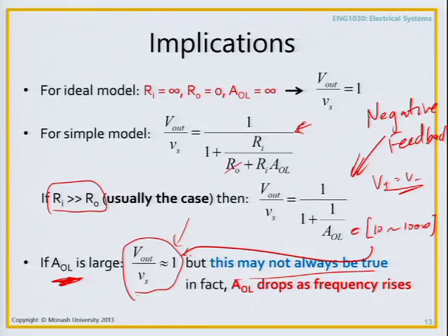Now, if I start putting a few resistors in there, and it's not a unity gain buffer, all the maths is exactly the same, and it will come out pretty much to the fact that AOL being large makes it so that we simplify everything by saying V plus equals V minus. Okay, so I've given that to you a little bit backwards, but there was a reason for that, which is I wanted you to start using the op-amp before fully understanding what's going on. So this is why negative feedback allows us to not be stuck with AOL as our gain factor.